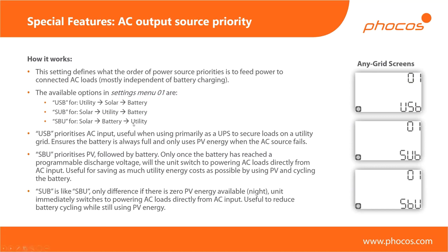So that's this last scenario where, again, you want to prioritize PV to save utility costs, and you also additionally want to make the most use out of your battery to be able to use every watt hour that you've captured from solar.